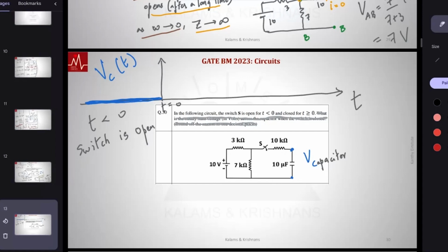Eventually, let's also see what is happening. Eventually, it goes to 7. Eventually, it is at 7. It's like exponential decay, but as you close the switch, all of a sudden you're applying a voltage. It saturates at 7, and there is exponential saturation. Initially there is a lot of change, then the change becomes smaller and smaller. It's just 1 minus exponential decay, saturation. I also want to get this bit somewhat correct.